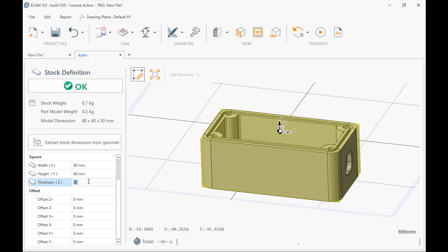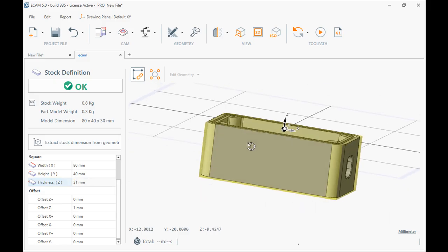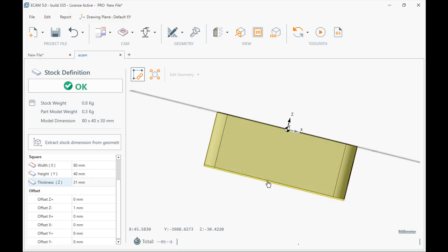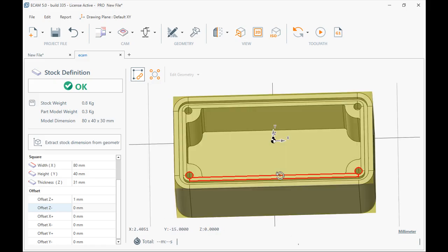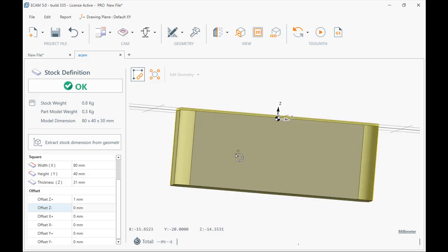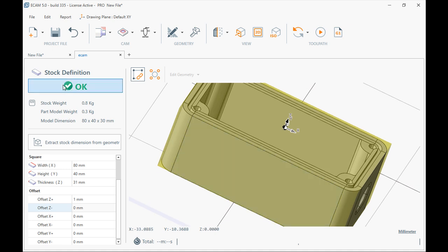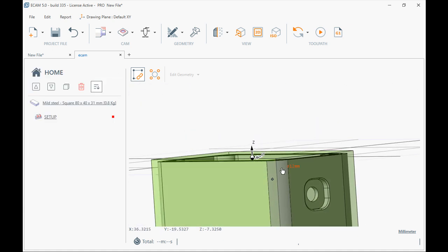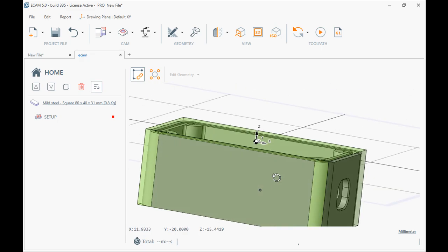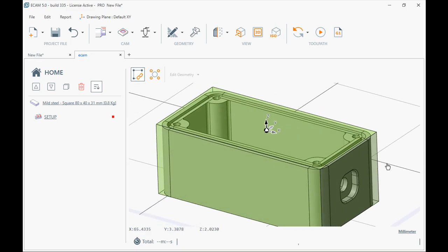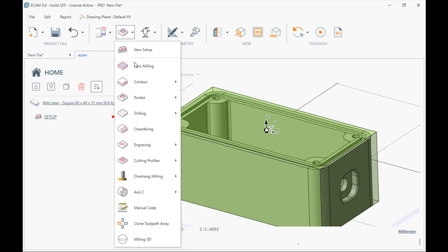I want to create an extra millimeter on the top. Okay, but it created it down. Let's invert, and I think it's done now. Okay. Doing the okay, and we are ready to start doing toolpaths. First one will be a cleaning program, call it facing, so face milling,